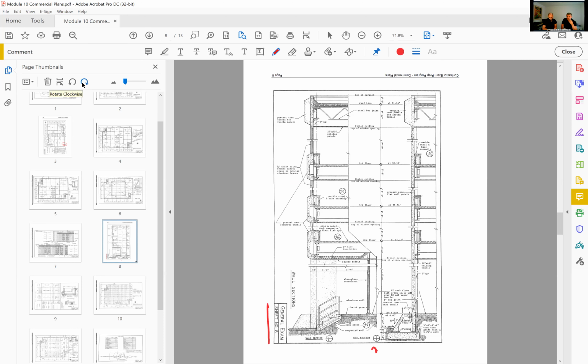You can see here, just what we were talking about before, we're cutting through that wall. Real quick before we go, we have 2 wall sections. This is saying that there's really 2 different types of walls in this building. Each different type of wall would have its own section. If it was a different size or different material or anything different within it, it would have its own drawing. Like Chris was saying before, in the real world you might have 20 different wall sections, especially in a custom home or something like that.